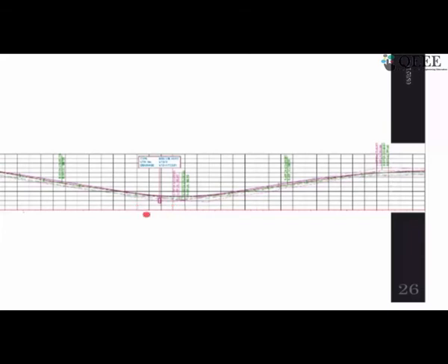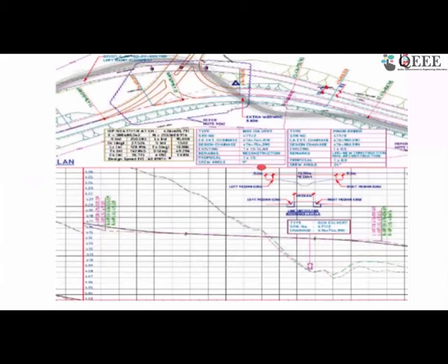So when someone is reviewing or designing, they need to make sure that there is a cross drainage structure and sufficient provision for water to flow out. And this is the complete criteria of that. As I told you, the intersection should not be on the curve or on a flat section. So in this condition we are not putting the intersection right here, but before the curve. Another thing we are seeing is that the intersection, wherever it is meeting, is on a bit flatter terrain or flatter gradient. This is how we make sure the design is proper.